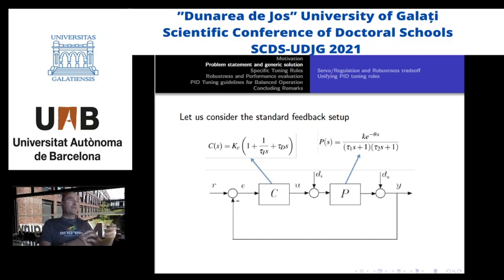And as you will see, we consider output disturbance, input disturbance, and reference, all the different signals that we will need to trade off. And very important, a second order plus time delay plant, where usually one can find in the literature just first order plus time delay.